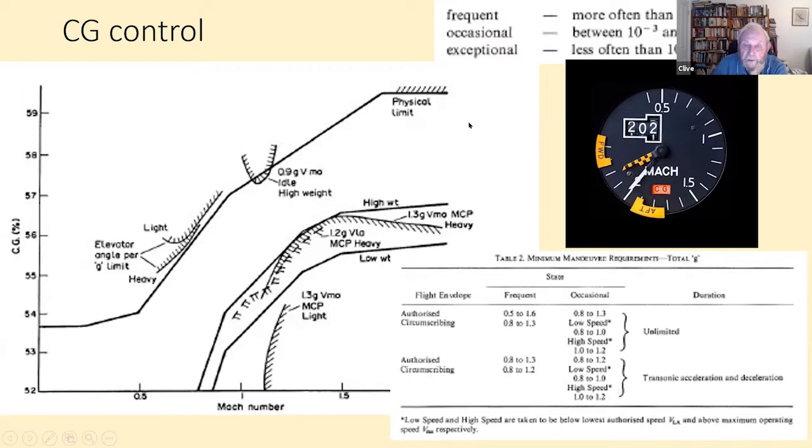It was certificated to a set of peculiar rules that were written for supersonic transports, known as the TSS standards. And they introduced something which I think was introduced into the civil aircraft field for the first time, which was that the flying qualities could be a function of how often you actually ended up in that state.